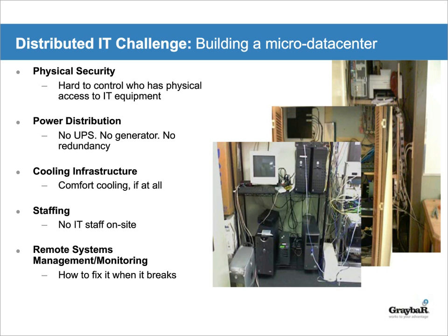A lot of times, with power distribution, people know they have to buy a UPS. So they go and buy a UPS, but they don't monitor the battery. Right? So you know what happens. After 3 years, whatever, when the power goes out, the battery is not working anymore. They were not monitoring that battery, and they didn't know they had to monitor it and replace the battery every so many years, right? So you end up with a lot of deployments that could be a whole lot better, right? And that's part of our job here, as vendors, to help those IT people make better edge IT deployments.